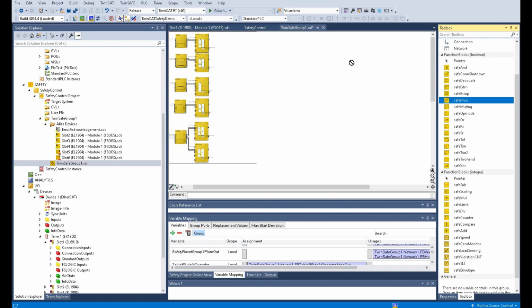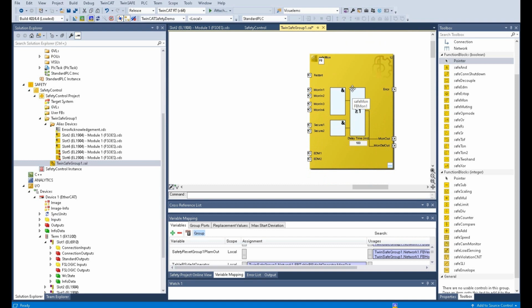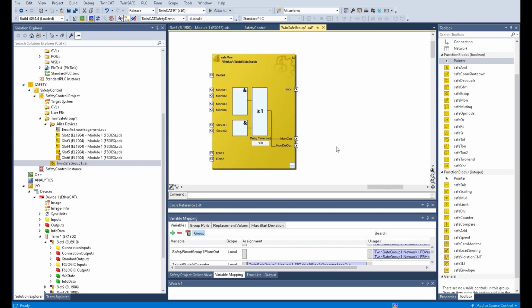Let's drag it out, and we can leave this area for the logic. We zoom in. This function block can be used to enable the valve bank at the turntable B side. Function block valve at table B side enable. And our control signal will connect to this monitor number 1 and number 2 channel.